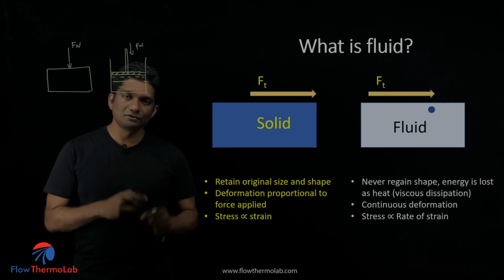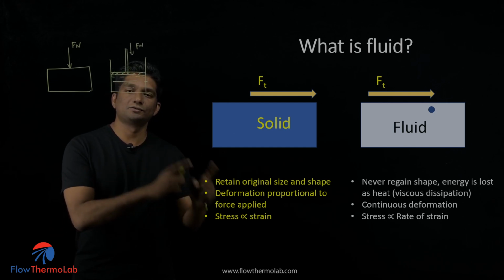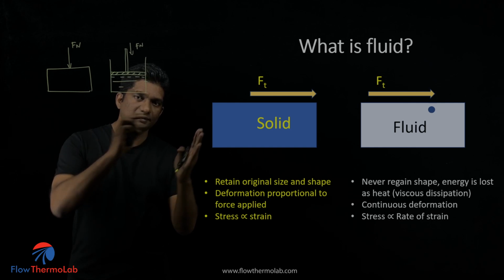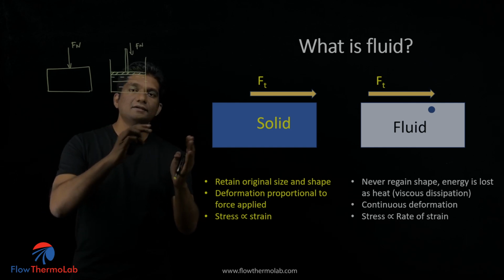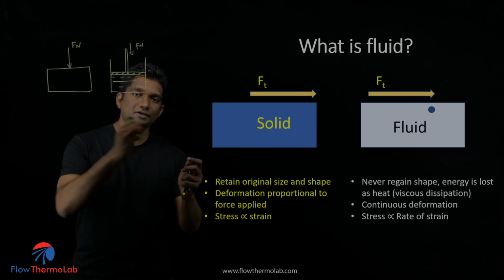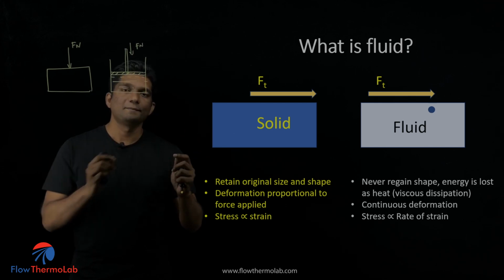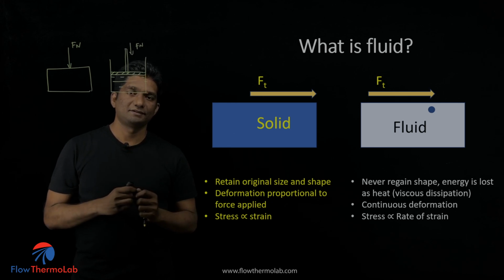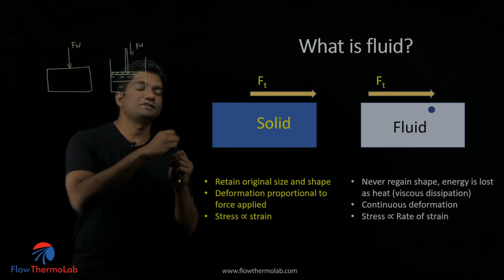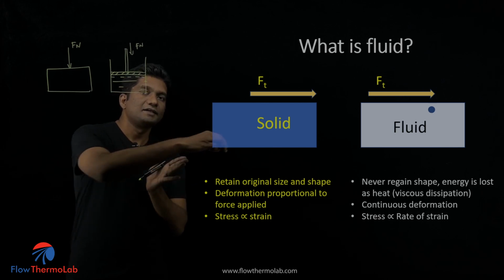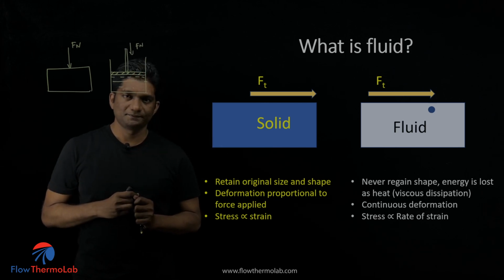One more thing you need to note: stress is proportional to the strain in solids. So you apply a force, it will undergo deformation, and the strain is directly proportional to how much force you are applying. But in fluid, it is not the deformation but the rate of deformation. So it is the rate of strain: how fast one layer is moving over the other layer.